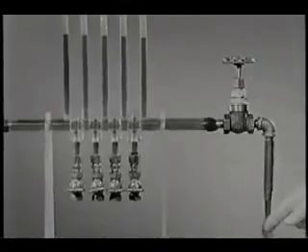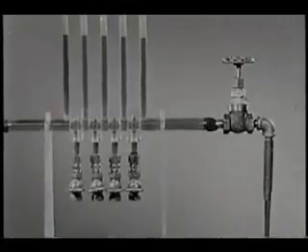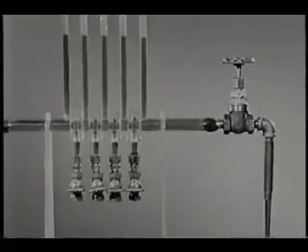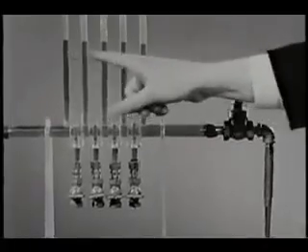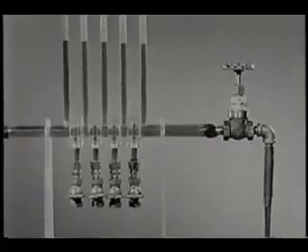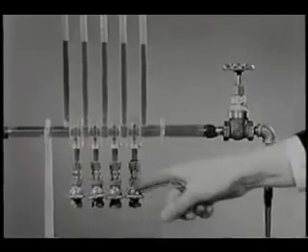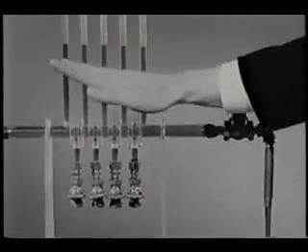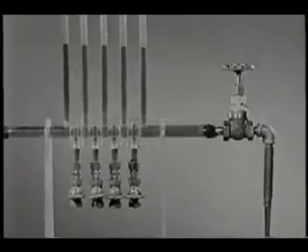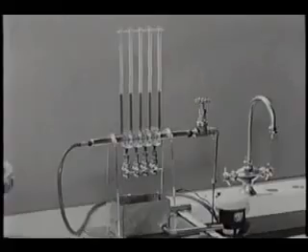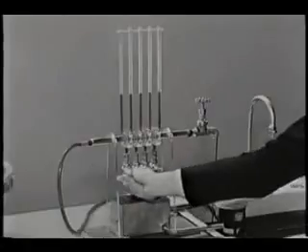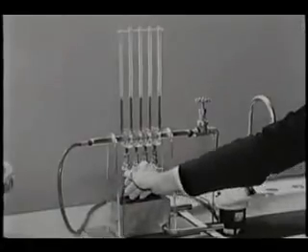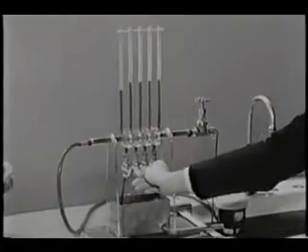This is a manifold. The pressure distribution is shown by the water levels in these manometer tubes. With the bleed valves closed, the average water velocity is the same at all cross sections, and there is a very slight pressure drop due to viscous forces. I'll reduce the volume flow at successive sections by bleeding water from the manifold.